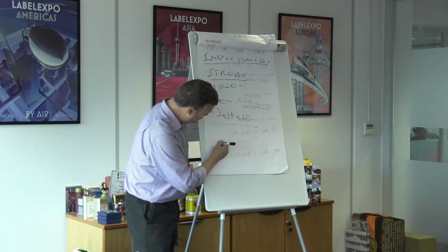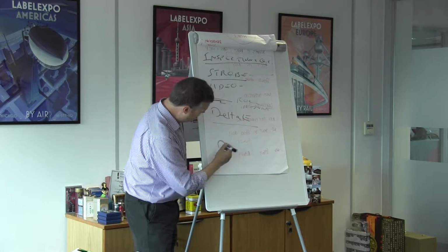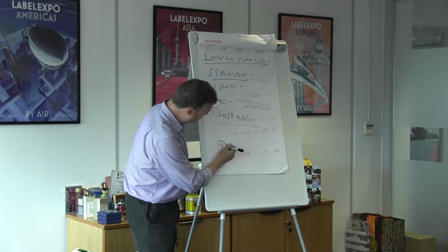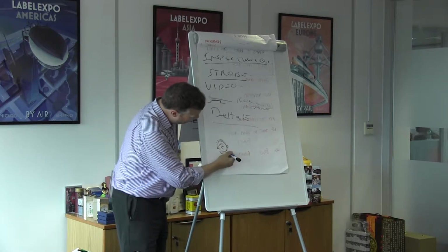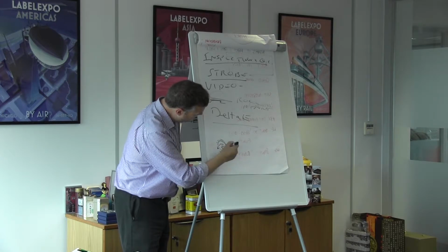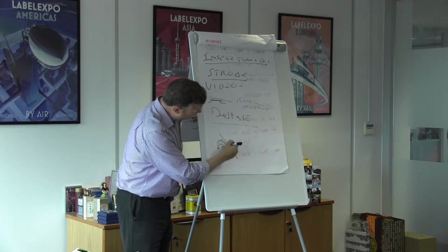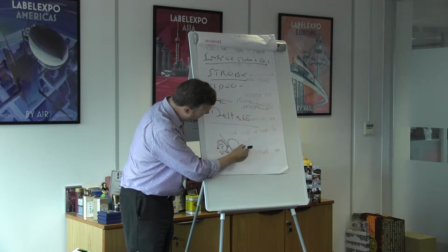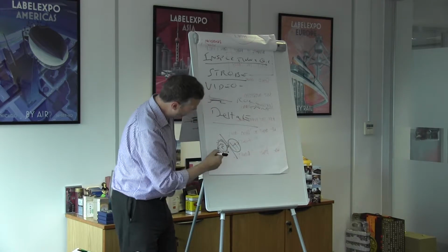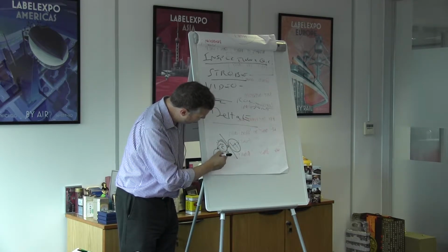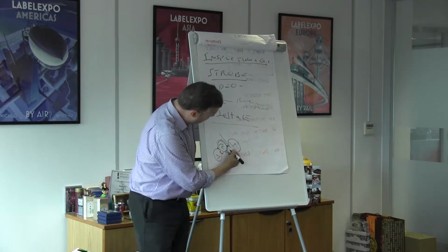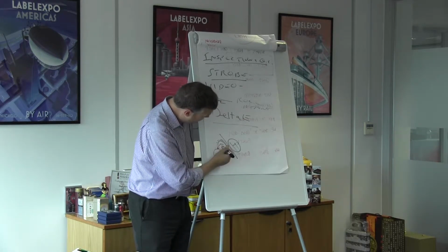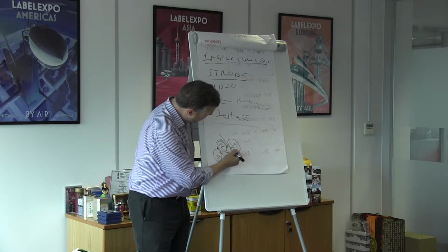So that's your plate cylinder. Again, the plate's standing up like that, and the ink is sitting on top of the dots. And you're running that against your material. You've got your impression cylinder there, just holding it in place. And you've got your Anilox roll there, which is putting ink onto the plate. Okay, so that's what you want to control. You want to control the pressure between that and that.